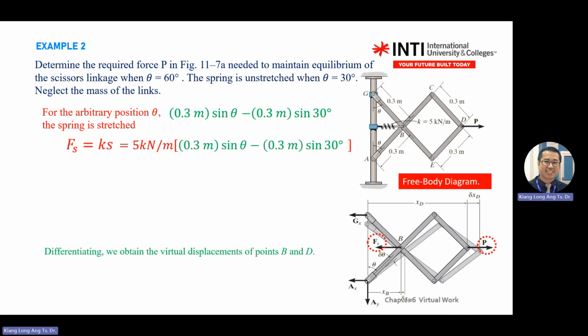So spring force equals Ks, then you substitute the equation and you get one equation first. So for statics or dynamics, don't substitute values in first. Derive the equation, then only you substitute. If not, you're going to miss out the relationship between the unknowns.